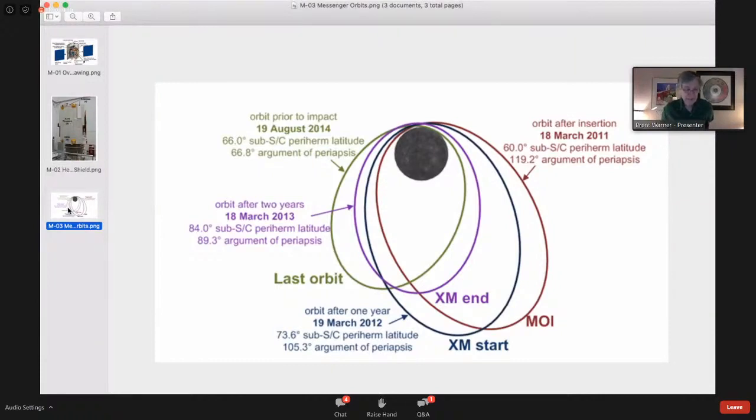But when you're passing directly over the really hot surface of Mercury, those radiators are getting all this infrared in, and they're getting pretty hot. So the diode heat pipe is a type of heat pipe that automatically turns off when the end that is supposed to be connected to the radiator, the end that's supposed to be cold, gets hotter than the hot end, the end that's connected to the hot electronics box.